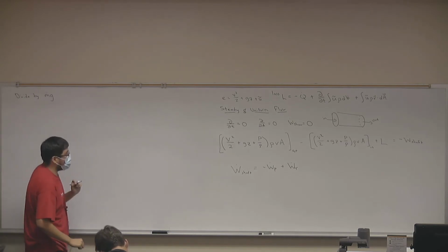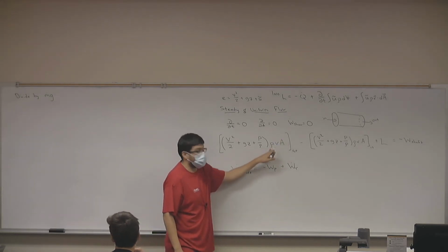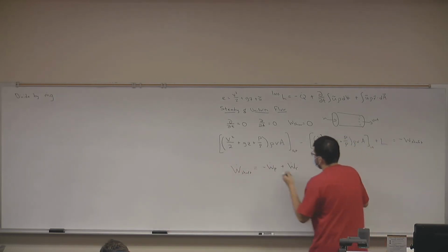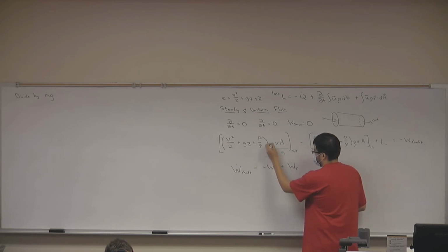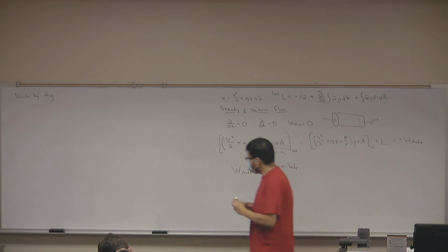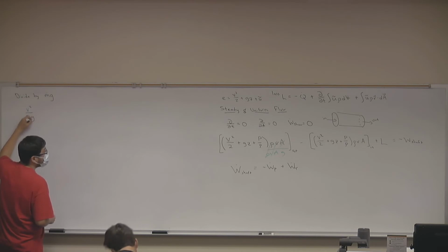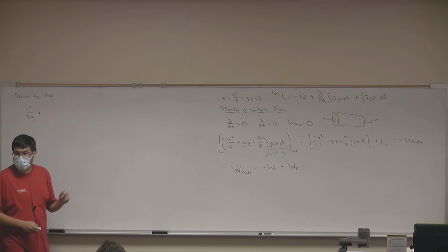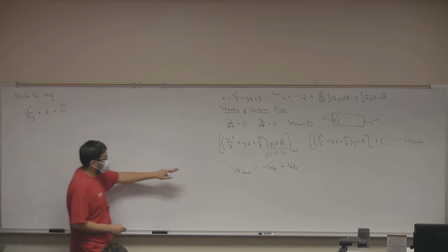And then what does my equation look like? Mass flux is density, velocity, and area, so all of these cancel out. Is that correct? Perhaps let me write it here. Mass flux is density, velocity, and area, and then I have my gravity. So we can say that these three terms cancel out, and I end up with velocity squared over 2g plus gravity times elevation over gravity. How much is that? Gz over g. Just z. Plus pressure divided by density times gravity.